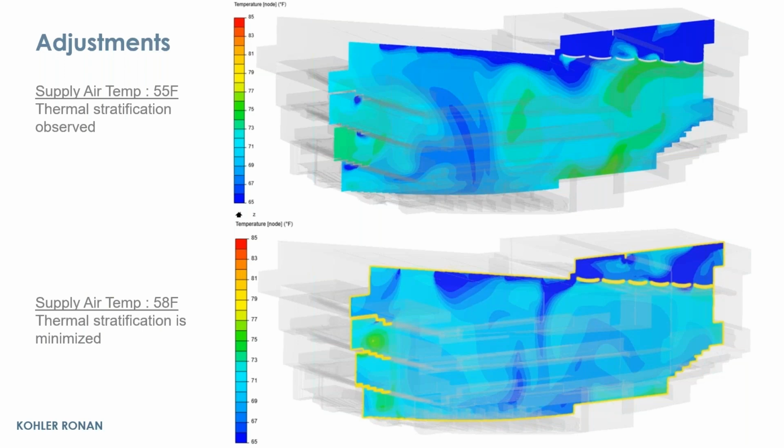When we started testing, like I said before, we moved airflow from the front to the back, and we started looking at air temperatures and stratification, and where we started finding those balance conditions, right? For one of the configurations we looked at, we found that supplying at 55 degrees in a fully saturated space, we still experienced some downdrafts and these central columns of cold air. When we relaxed to 58 degrees, it became a more homogeneous, more mixed condition, and comfortable again for the occupants.